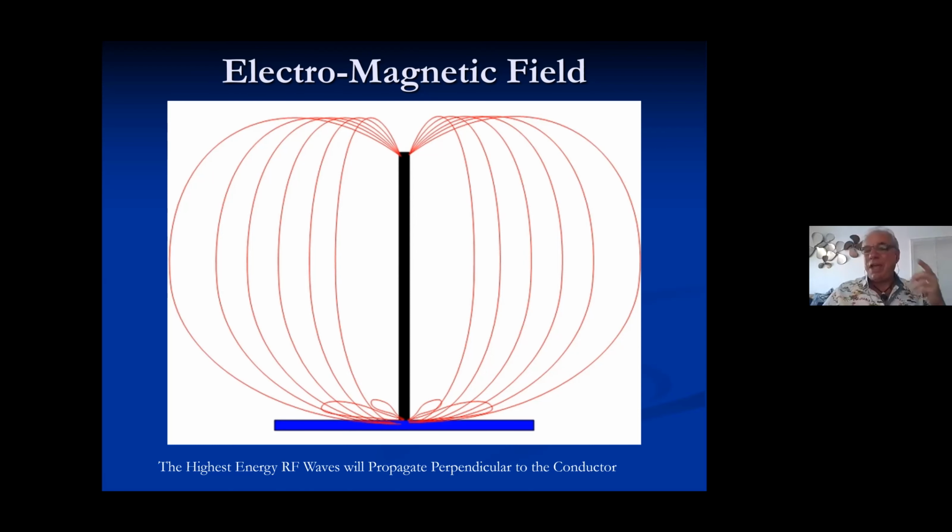If you take that same 5,000 watt amplifier and plug the speaker terminals into one end of a coat hanger and the other end into ground, that abundance of energy will create an electromagnetic field as opposed to an acoustic field or sound pressure level changes. Now, the reason that the radiation pattern of the antenna looks the way it does for this regular old common whip antenna, is because the greatest aperture, the greatest amount of surface area of that antenna is on the side of the antenna.